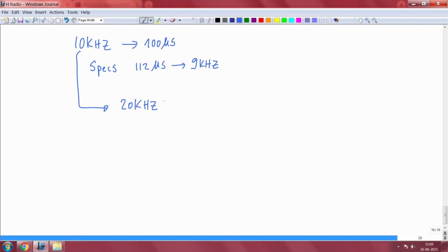Okay, you need at least 20 kilohertz. By the way, people interchangeably use 20 kilohertz and 20 kilo samples per second; both mean one and the same. So, I will replace this with 20 kSPS. It is easily connecting, right, because you saw the same number. 20 kSPS is something that you must minimum support if you are getting an input.